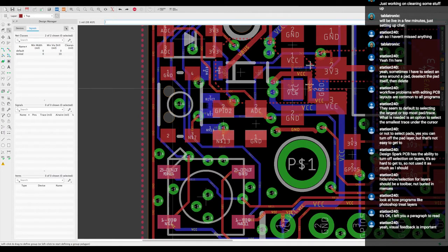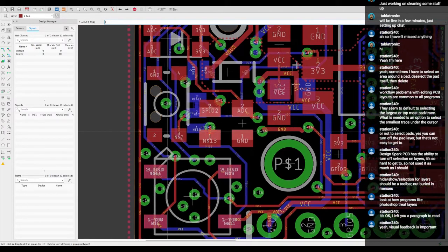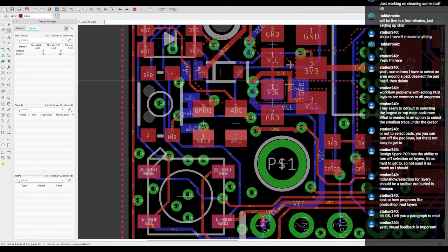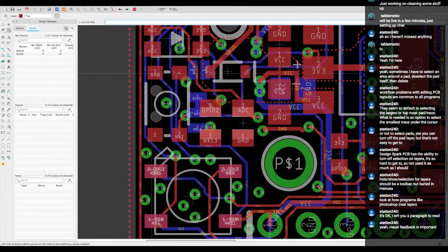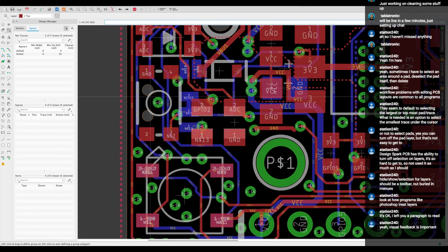And then I just modified this footprint so that each opposite corner has a signal, and these two are no connect. That's why this is warning me, because I don't really have it set up as that signal. It should work. I think that'll work. I have a few different buttons that fit that kind of footprint that can go on here. I might have to modify these pads a little bit, but for now I think I want to test that and see how it works.